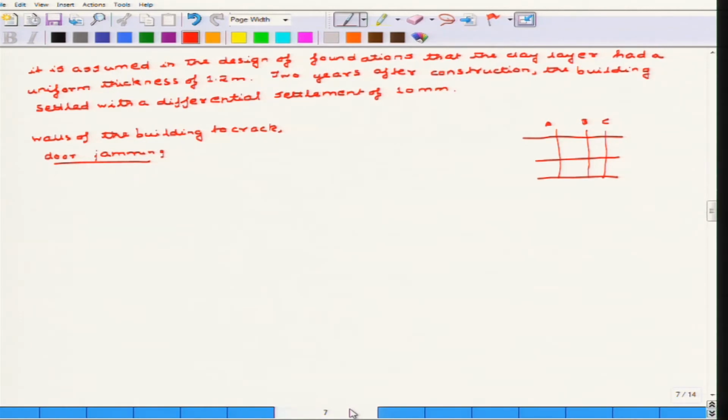So you have to perform a very proper soil investigation in order to know whether there will be a differential settlement or not. Different codes have also specified different measurements of differential settlement. There is only a particular limit to the differential settlement that you can actually approve in the field.